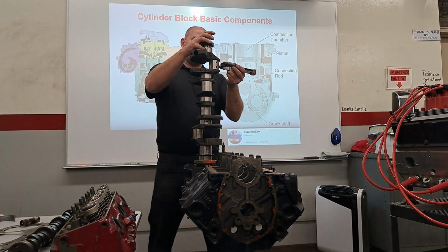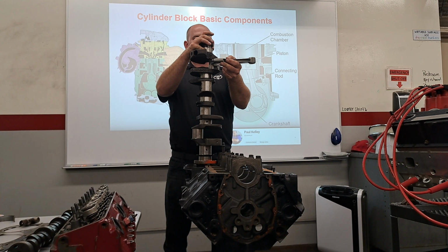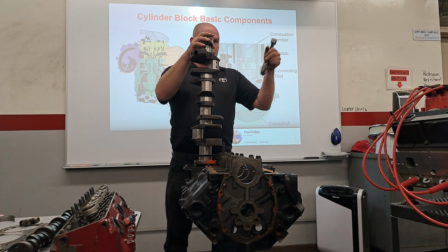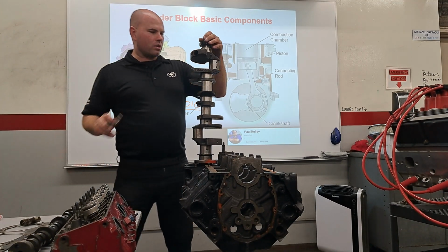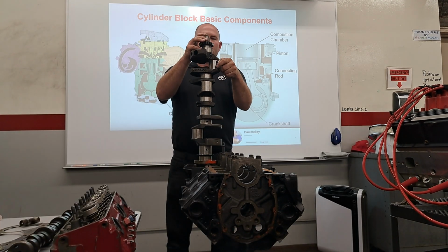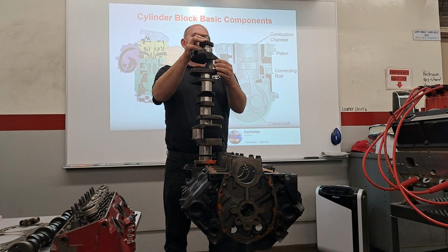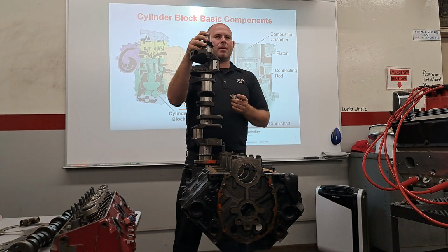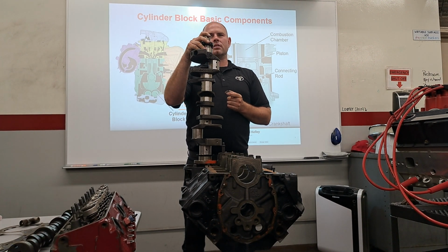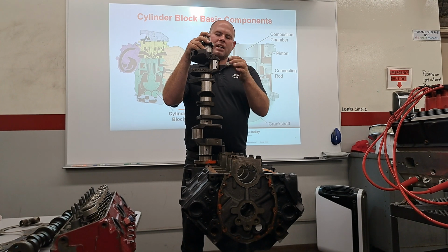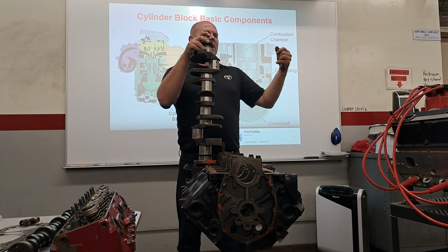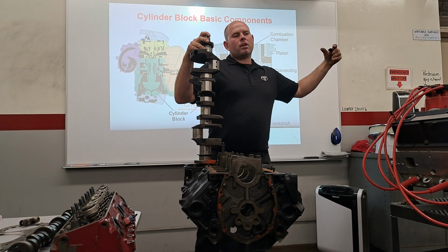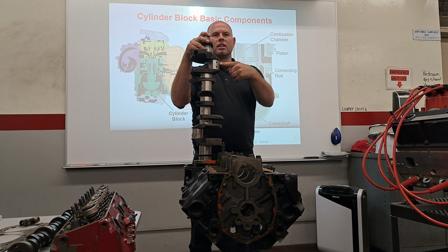Make sense? So that's actually going to get a rod, and then the rod is going to take a piston, and that's going to go up and down the cylinder. Those have bearings too. What do you think those bearings are called? Yeah, connecting rod bearing or a rod bearing. By the way, the connecting rod bearings have a harder job than the mains. That connecting rod bearing has to take all the force of that whole one cylinder and rod, right? So if that cylinder gets a combustion stroke, that connecting rod is being rammed right into this journal, just that journal and just that bearing.